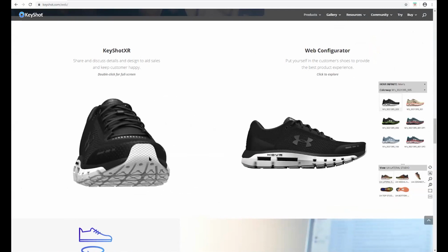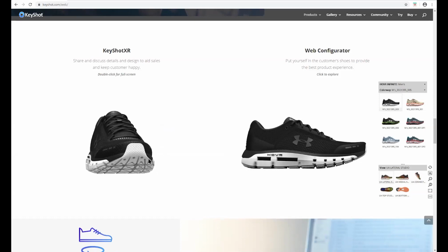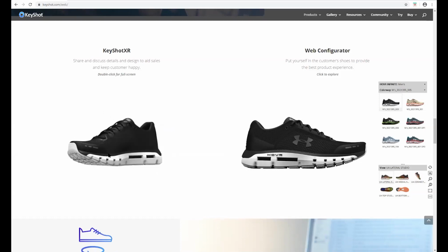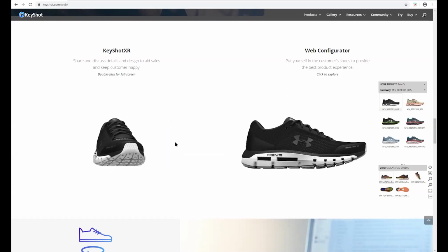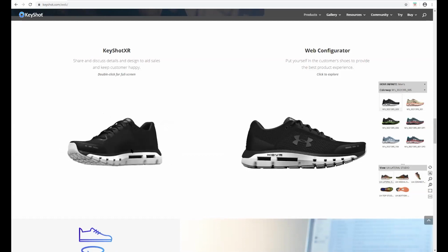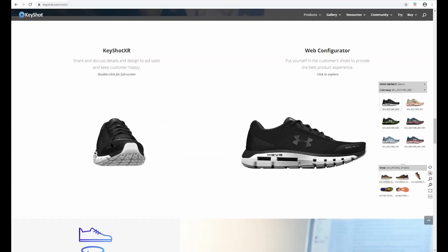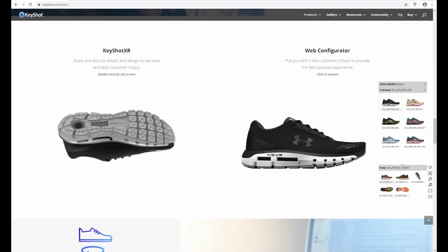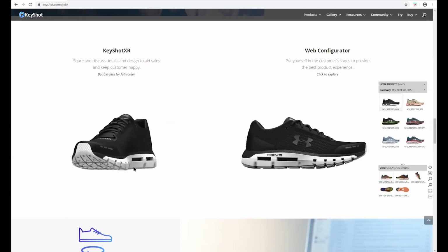Every single stage that it's closer, it's going to have to render all those views out. So adding the zoom is going to increase your render time. So do take that into account. If it's important that you're able to zoom in to a degree, it will take longer. If it's not important and you want speed, then I would recommend not using that and keeping it at a distance. It's still an extremely useful tool that you can see everything that's going on. So it's really a matter of personal preference and the turnaround time that you have.